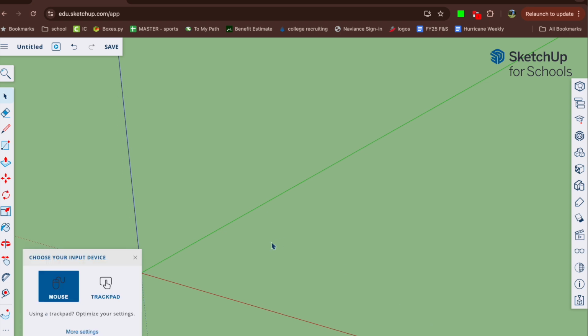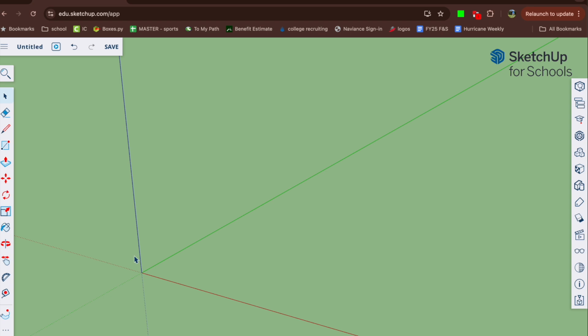And that reminds me, SketchUp is a click and hold or click and release button. So if I take the line tool, I click once and I let go, I can then drag this line in any direction. You don't need to hold down while you're dragging. So if I click and drag, you can do that, but it makes for awkward modeling where all you need to do is click once, release, and then drag to where you want. And I'm just Command-Zing on a Mac. You can do any undo depending on what computer software you're using.